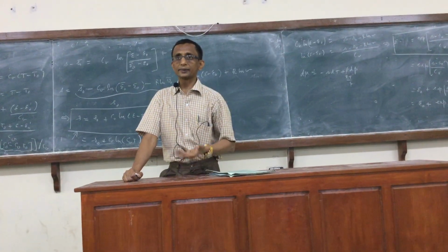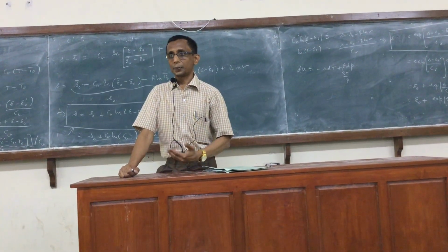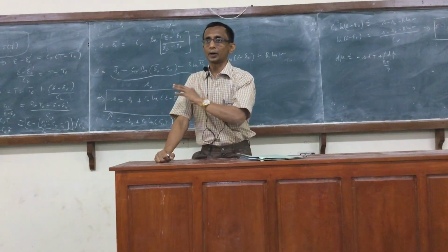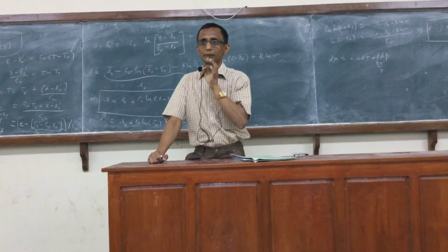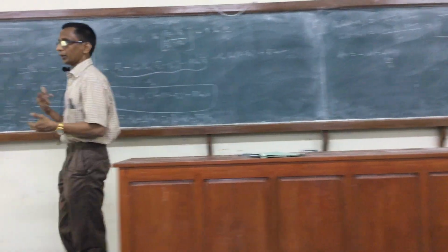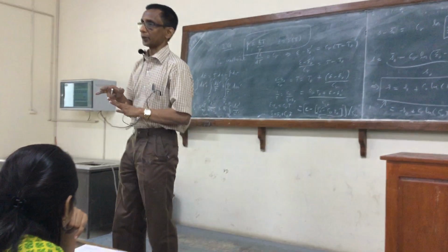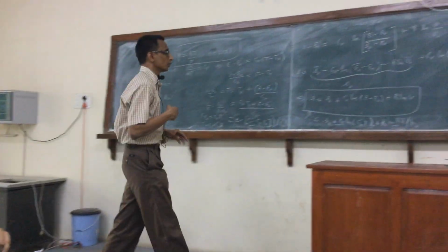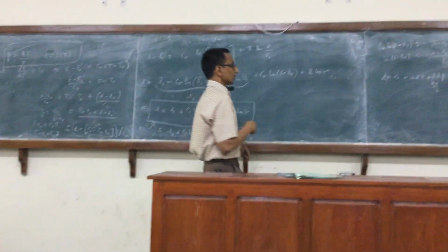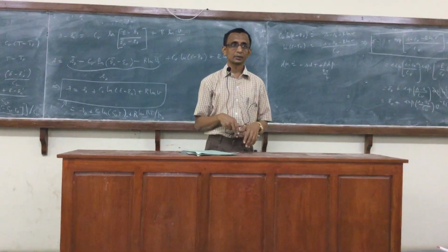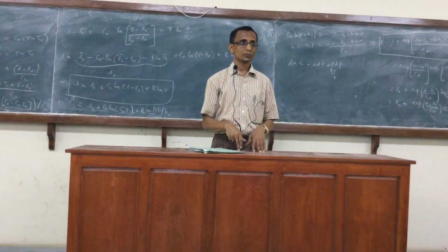Right? So the ideal gas, when specific internal energy is expressed as a function of temperature, it doesn't depend on any other variable, it depends only on temperature. But when you want to express it in terms of entropy, then you cannot just stop at entropy, the volume will also come in. Right? So those things you have to keep in mind. So these give some properties of the ideal gas that you should be aware of.